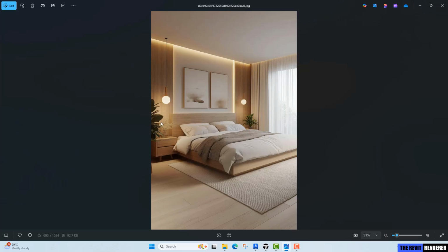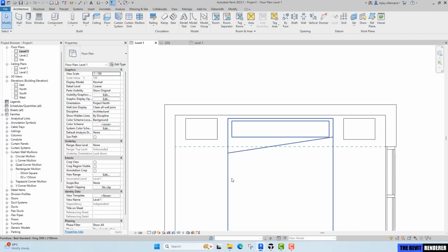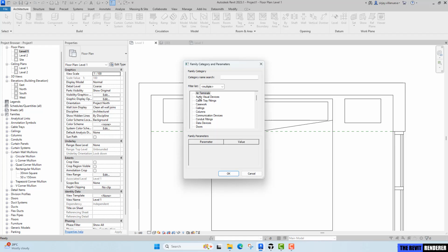design, there's actually a built-up wall here, like a wood paneling, and we're gonna create this using a model in place component. So let's do that now. I'm here in the floor plan again. I'm gonna go to component, model in place. I'm gonna put this under casework.